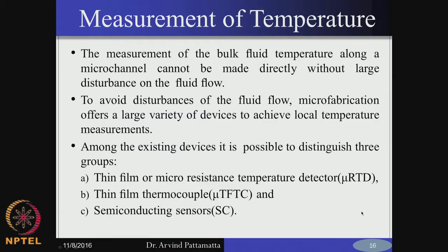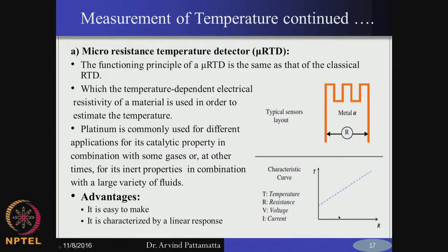So, this is basically the conventional way. We do not directly sense temperature, but indirectly using current or change in resistance or corresponding change in voltage, and which is quite accurate. If you look at the RTD, for example, you know the temperature coefficient of the electrical resistance. So, as the temperature increases, the electrical resistance could increase.